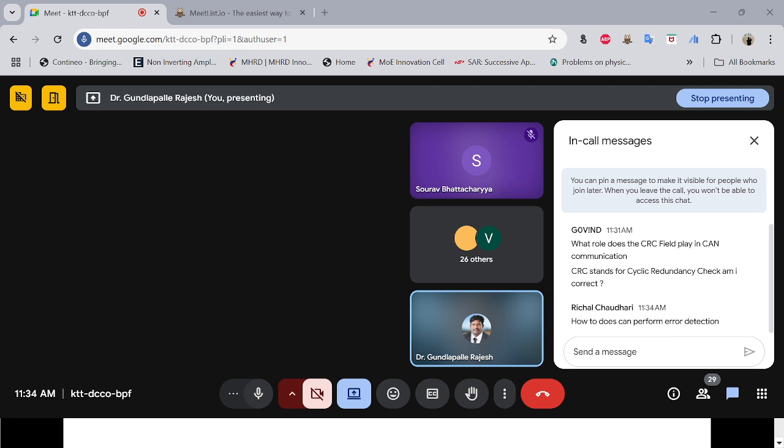Then how these frames are received. Node A sends a remote frame request, so it requests the frame. B, C, D receive the message, and only D accepts because B and C decline the message. This is the method of requesting, and this is the method of broadcasting. For broadcasting or requesting, node A, which is the center node, will send the request or send the data.